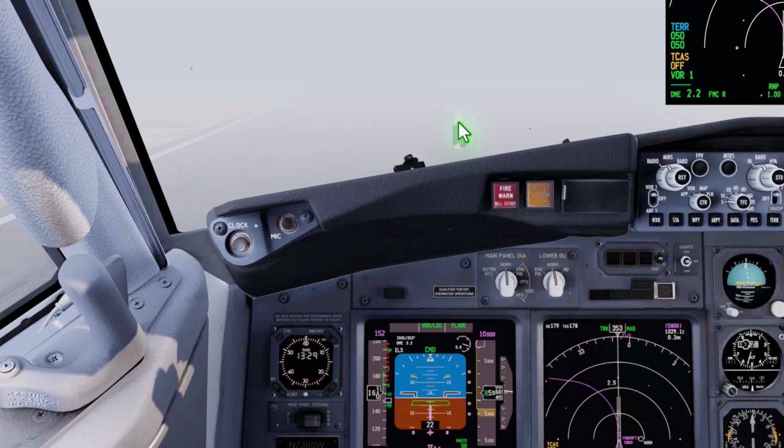I mentioned earlier, in these conditions, you may be able to have good visibility all the way down the runway to a stop and be able to turn off. But recognize, too, you could go into a fog bank and lose that, and then you may be able to pick it up again. Your airline will have some guidance and training on how to handle those kinds of conditions. Essentially in this case, because we don't have the localizer here, we've lost some ability to do it instrument-wise.